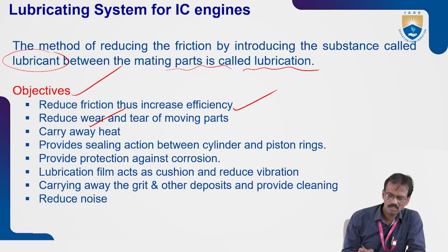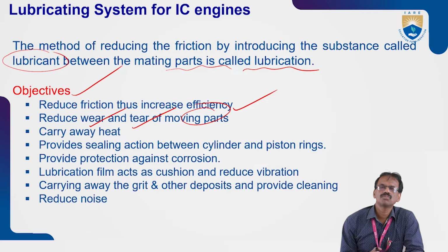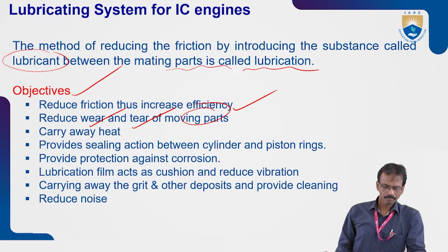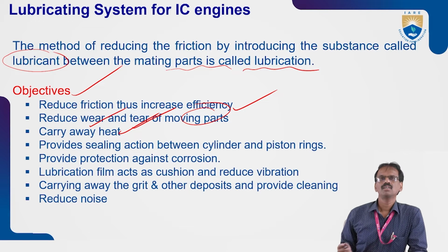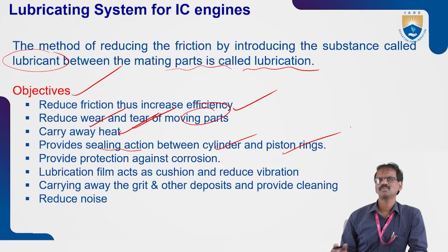So reduce wear and tear of moving parts, because overheat leads to wear and tear of the engine parts, mainly the inner surface of the cylinder or piston surface or piston overhead also. Next, to carry away heat, it adjusts the overheat by heat transfer modes like convection mode. It provides the sealing action between the cylinder and the piston. It also absorbs the shocks which occur between two mating parts.